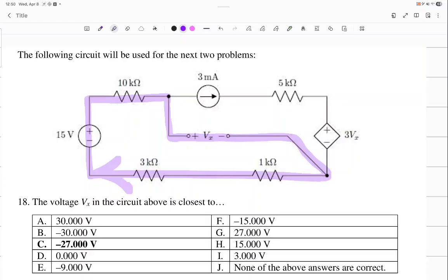And just, this is not about electrical engineering, but why did I include that? Why did I choose this loop or mesh for my KVL? Why didn't I write the big one? Because we can simplify all those individual voltage drops too. No, there is something wrong with going for the big one. You don't know the voltage across the current source, so you should avoid that. Right? Do you know what's the voltage across the current source? No. So I'm trying to bypass that.